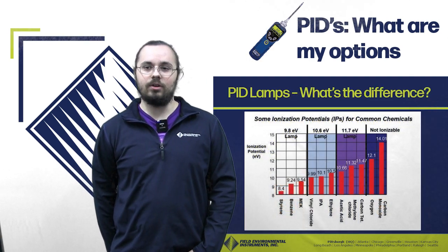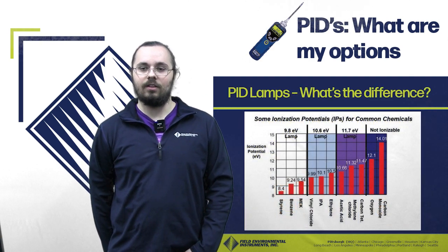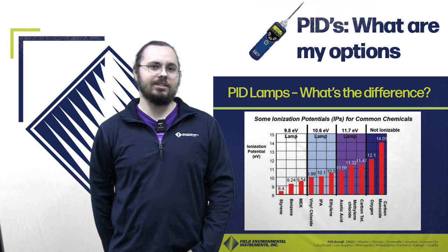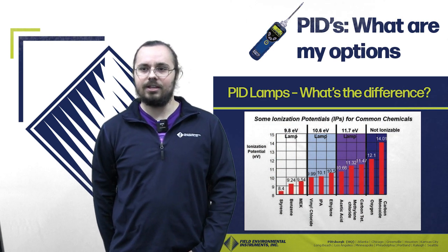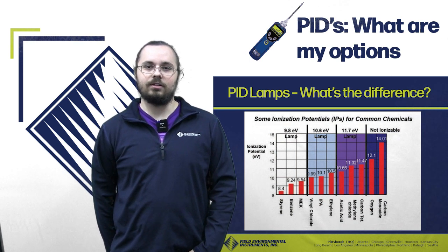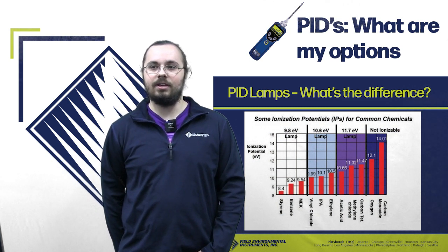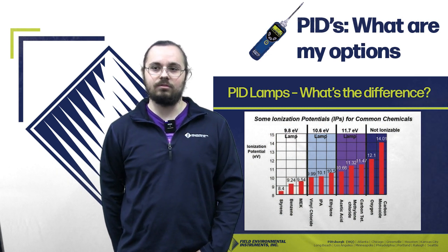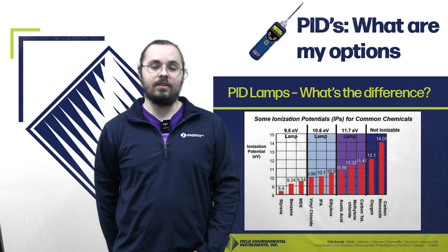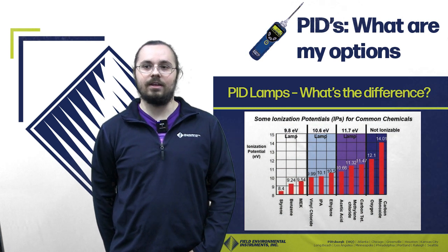So, PID lamps. You'll hear this a lot when you're talking about PIDs. A lot of them use different lamps. What exactly does this mean? Essentially, they're measured in electron volts, which depends on the compounds that they can detect. Higher eV lamps essentially mean they can detect more compounds with a higher ionization potential. Any gas lower than that value can be detected by that lamp.